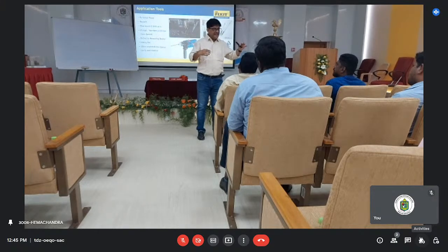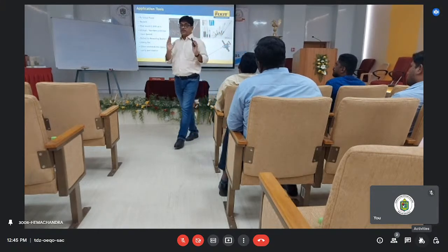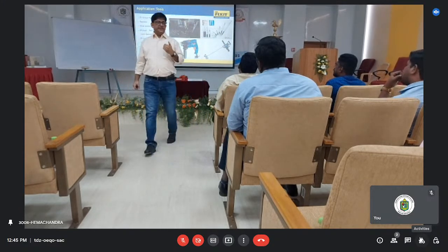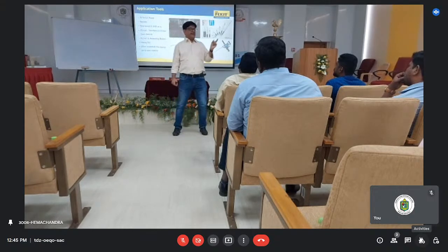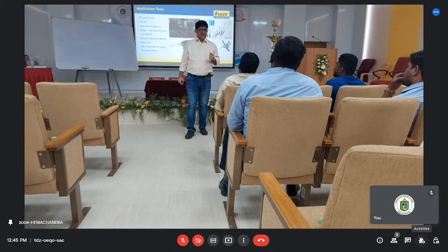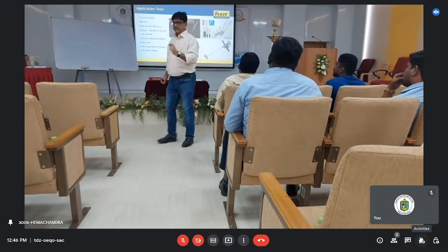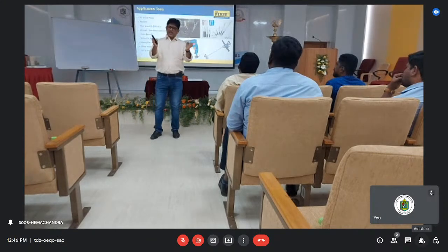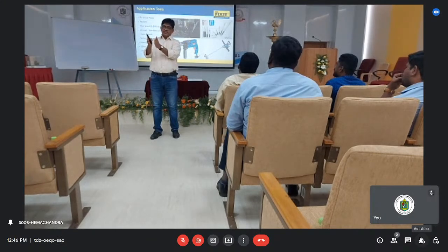So my drilling has to be minimum 2/3 or 3/4 of the baseline. That is why when you do a PU foam injection, before that you first have to check where my rebars are. I should not drill through the rebars. First I have to check where my rebars are. Then I have to drill through the line, and I should reach the minimum 3/4 depth of the span.